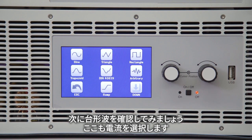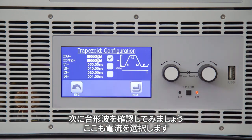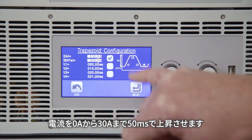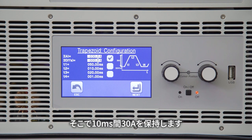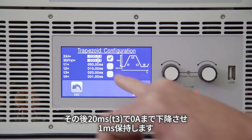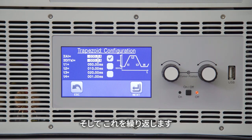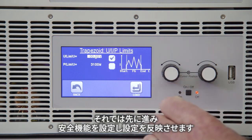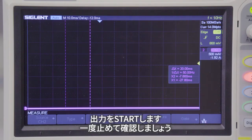Now we'll take a look at trapezoid. What I've done is programmed a current here, saying I want to go from 0 amps to 30 amps over a period of 50 milliseconds, stay there for 10 milliseconds, ramp down T3 at 20 milliseconds, stay there for 1 millisecond, and then repeat that sequence. We'll load it in. Of course, you have your safety features as well. We'll load it and start it.